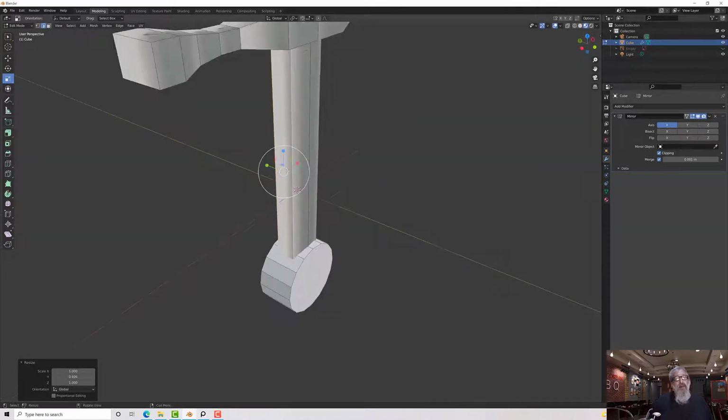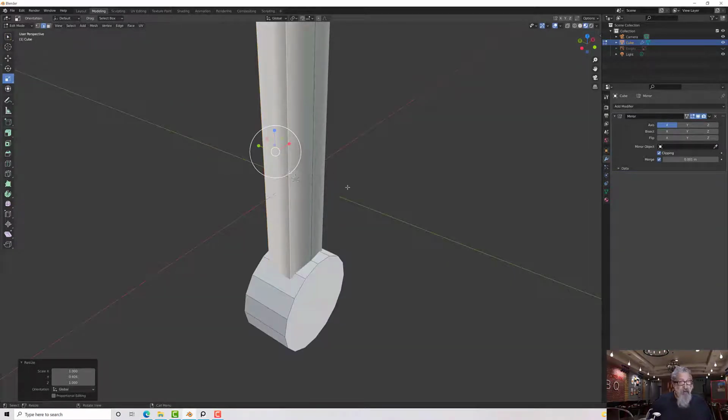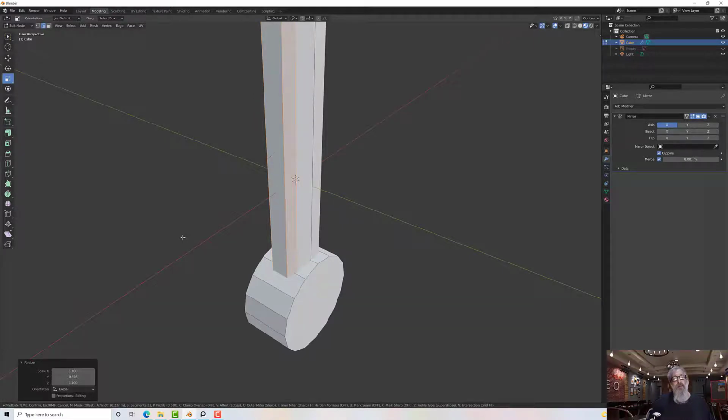And then we want to bevel it. For bevel, we press Control and B. It's B for Bravo. And you might move it around and find it doesn't do an awful lot. I find it's best, if you see that little dotted line, to go to its origin and then move away from the polygon in that direction.